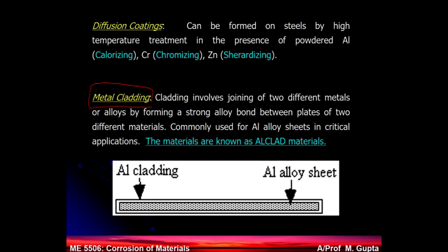So they take this high strength aluminum sheet and aluminum foils and they sandwich them and roll them together. So Al-clad, Al stands for aluminum. Clad means now this high strength alloy is cladded by single phase aluminum, no galvanic cells. So your corrosion resistance is better in the normal situation. So they are called Al-clad alloys, commonly used in the aerospace industry.